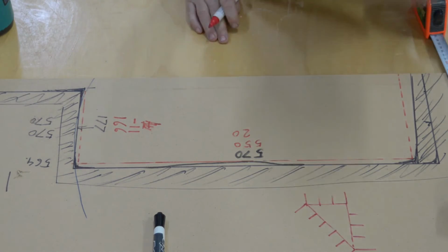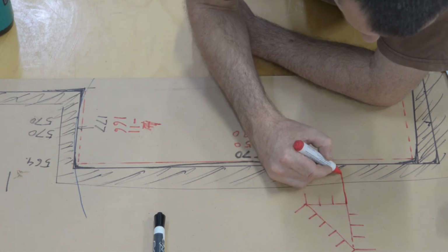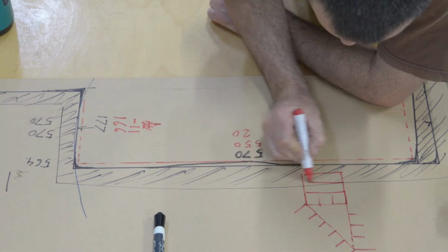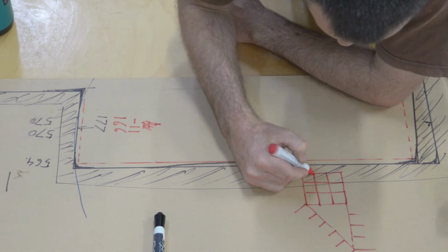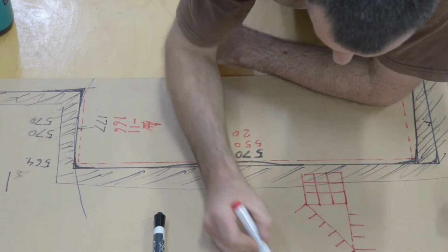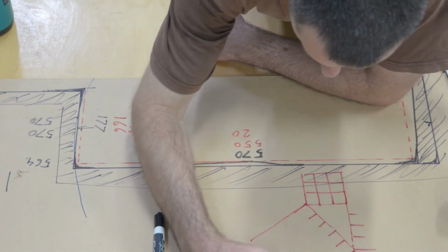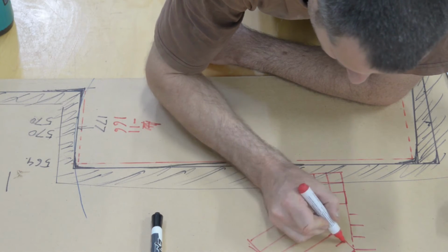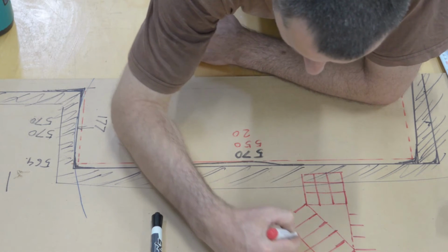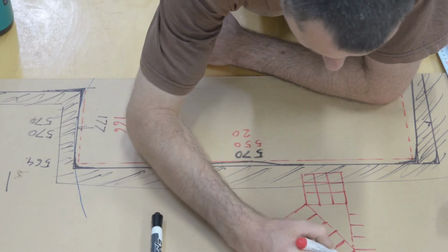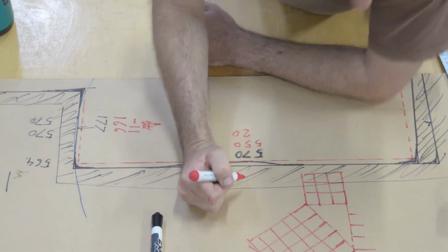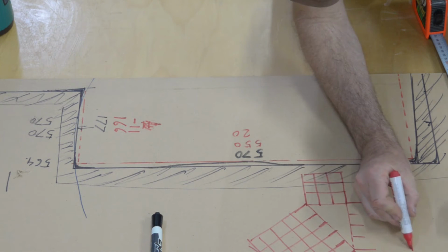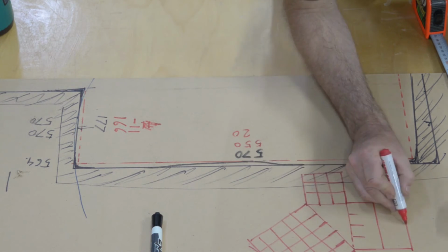Now, a visualization I use to explain this to students and whatnot. So, demonstrate this being a set of squares. Now 3, 4, 5 is a handy number to use because they're quite easy numbers, and it doesn't matter what kind of unit you use. If you remember 3, 4 and 5, you've got yourself a measuring tool for square.